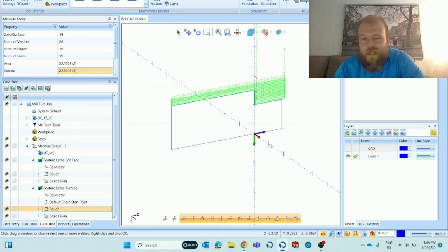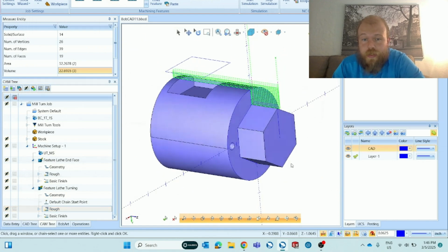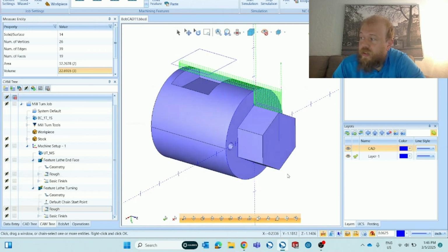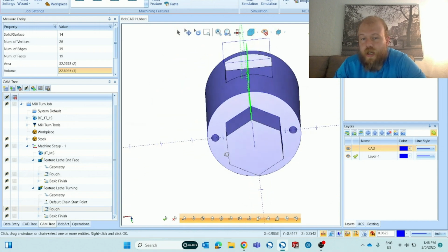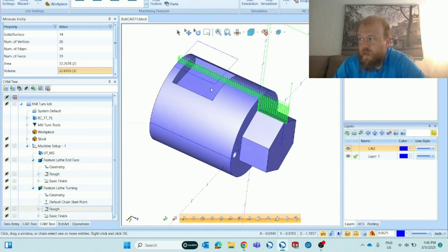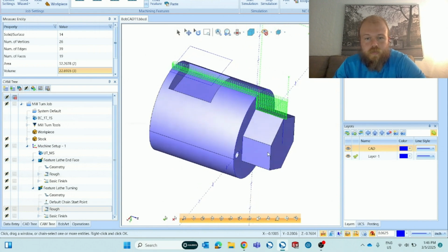Thank you guys for bearing with me with the sort of discrepancies of having to rotate the wireframe after using the spun profile and anything else that we may run into. I am starting from scratch with this 3D model. So if you guys are just entering the live event today, you can go back to it at any time after the live event is over and be able to see how I created the hex, extruded it out, created the OD and extruded that out, did an extrude cut for the holes and the pocket that we're going to be going over next. All right, cool.